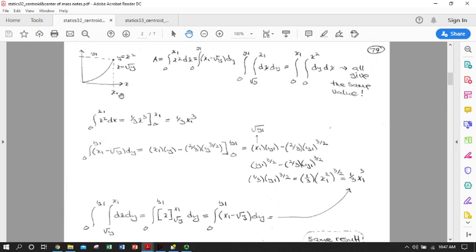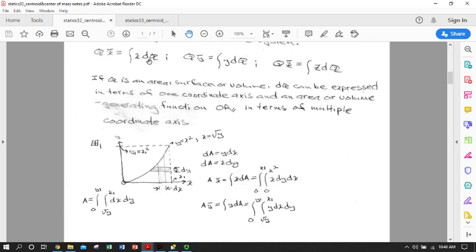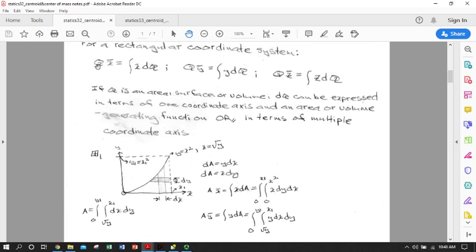Having done that, we're going to go ahead and actually evaluate the area using our limits, and because I'm familiar with integrating with x as being my independent variable, I chose to integrate this one and calculate area that way. So I integrated x squared dx from x equals 0 to x equals x1, popped in my limits of integration, and I got 1/3 times this x1 limit, which is some number, cubed. So that's my area A. And if I were looking up here in the general definition, that's effectively Q.